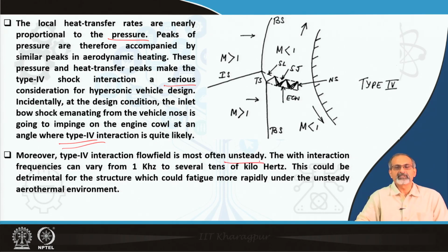The interaction frequencies can vary from 1 kilohertz to several tens of kilohertz. This could be detrimental for the structure, which could fatigue more rapidly under the unsteady aerothermal environment.